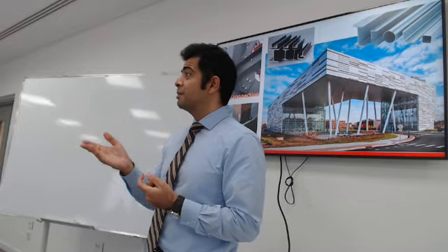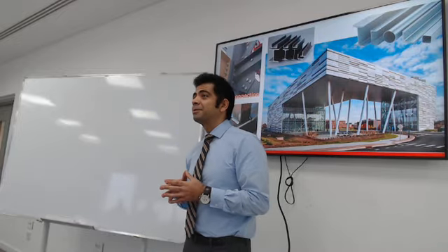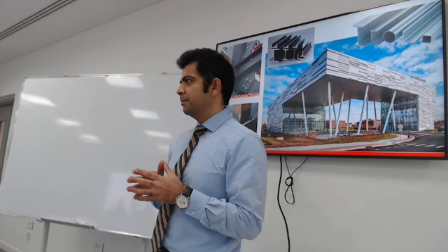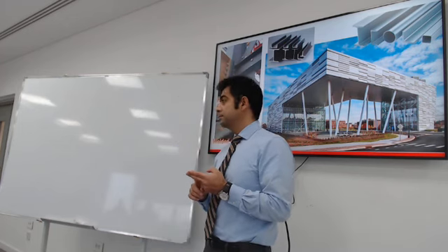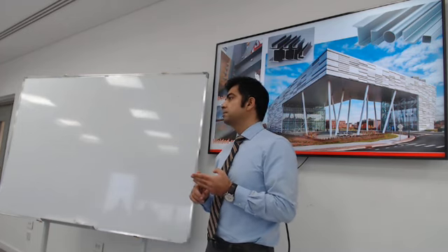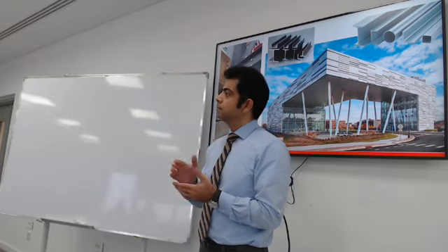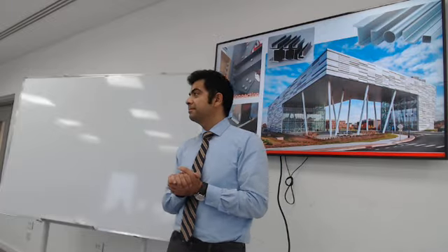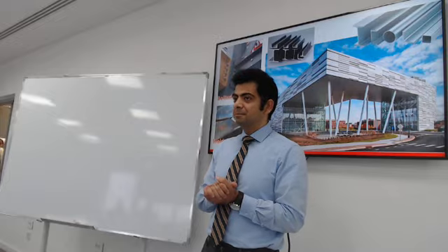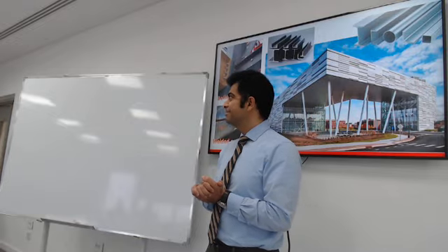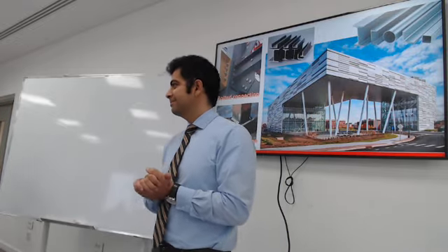Done design of beams. Do you guys know how to design a beam? How to design a steel beam? Anyone can quickly summarize how to design a steel beam? Yeah. Calculating the moment and the shear and all the forces, and then you find the moment of inertia. Select a beam from the table. Yeah. And then you have to check if this beam will support the weight, the moment, and the moment of inertia that you calculated to make sure if it's safe or not, or satisfactory or not.